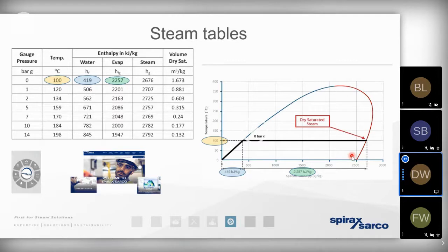And if we've got an excess of liquid condensate that's held back in the distribution network, we need to remember there's far, far less energy in a kilogram of condensate than there is in a kilogram of steam. So we need to get that liquid condensate away very, very quickly. We do that by passing it across steam traps. So the wetter the steam, the more condensate there is, the more steam traps we need to design, engineer, install, procure, maintain, and so forth.